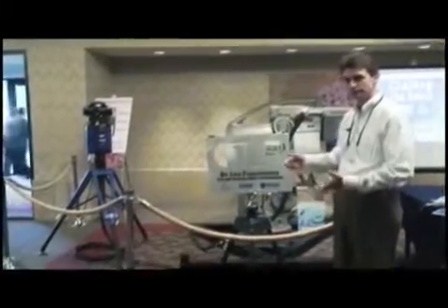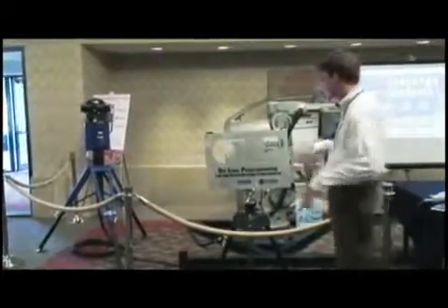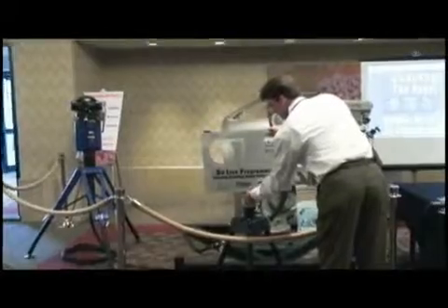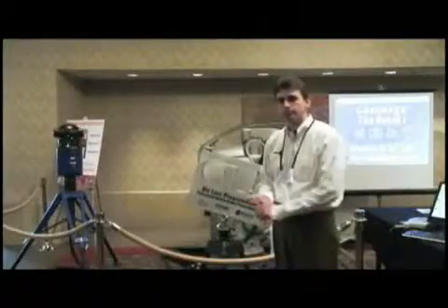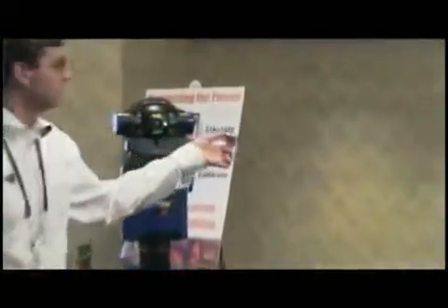First thing I would need to do is to change the plate location into some random new position. So I loosen this and just turn it. So now obviously it's way off from where it was before. So the next thing we have to do is measure with the laser tracker. So first I'm going to go and pick up the SMR, the probe. And I'll use this to measure 4 locations on the plate.